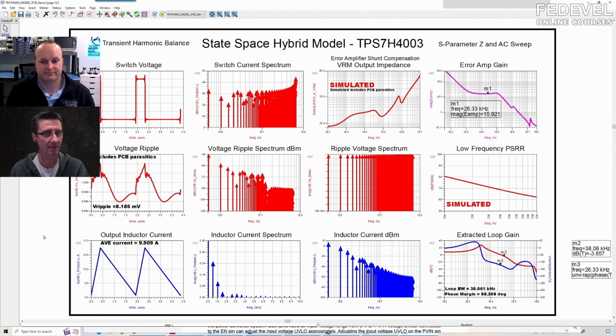So did you fix this? Well, the question is, how do you fix it first? For me, I go back to my bread and butter, and I can't emphasize this enough: impedance. Remember what I said a second ago? If you remember one thing, noise follows impedance always. Remember, V equals IR. If we change that R to a Z, we've made it into the complex term of impedance, real and imaginary.